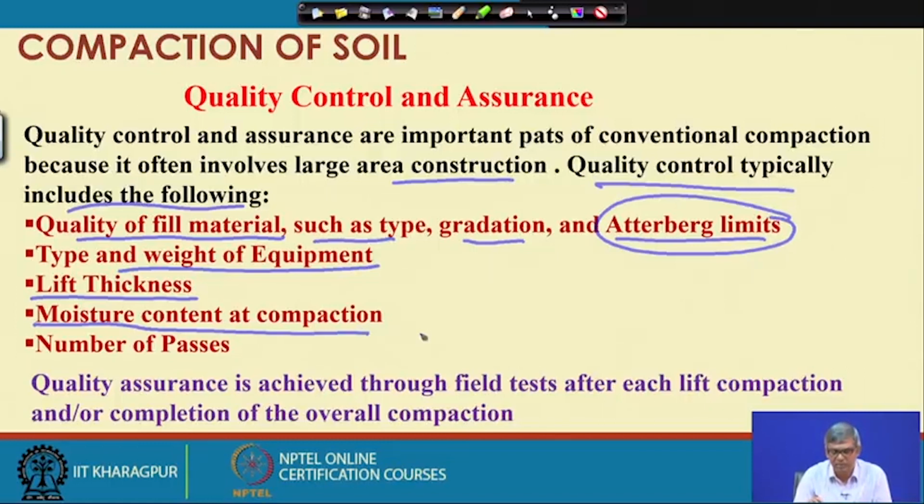If the moisture content is less or more than that, you will not get it; only within the range do we get it. So you have to see whether sprinkling is being done or not. And the number of passes is also very important. If 4 passes are recommended but more or fewer are done, both are sometimes not correct.